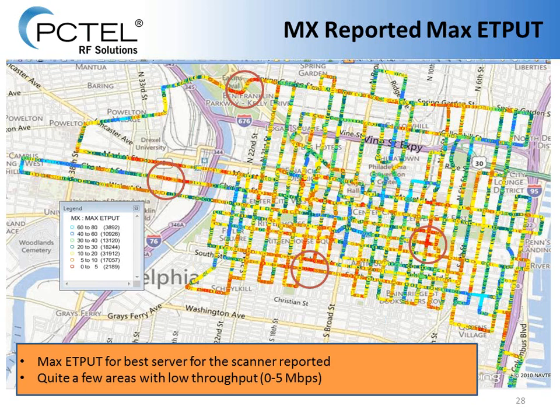And number two, it's not going to be capped, because what this does is it looks at what the RF environment is like, as well as what the MIMO parameters are like based on the CINR and how the antenna is set up. So consequently, we're going to report what the maximum estimated throughput is, what the environment is capable of putting out for throughput in an ideal situation.